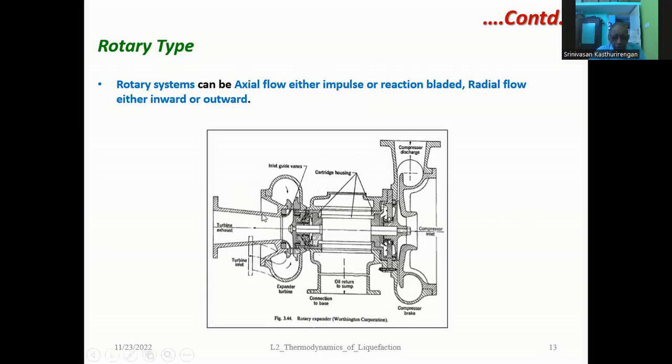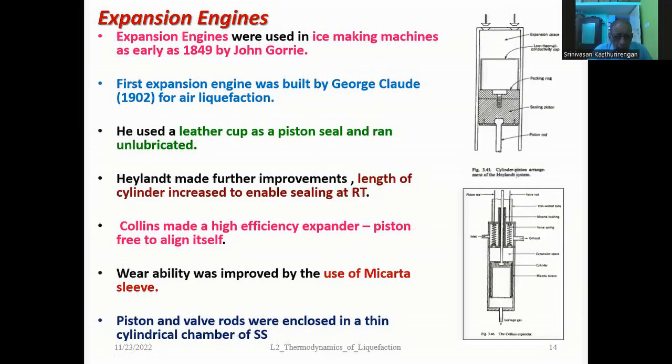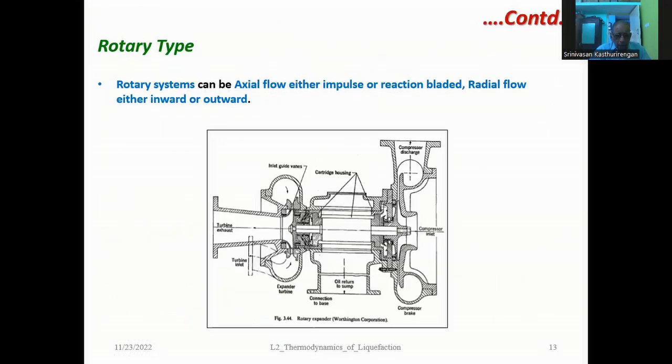I think I have to just mention briefly about the expander parts. I will just talk about the expander first. In the expander, the gas is coming in and it has to be expanded to low pressures so that it does work on the environment, on either the piston or a rotary blade, so that the gas gets cooled.